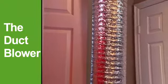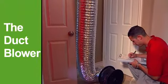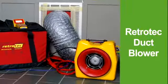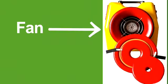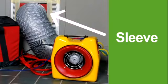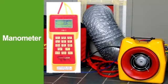We'll start by introducing you to this piece of equipment and then run through the procedures for testing total duct leakage. There are a couple different types of duct blowers on the market. In this video, we'll use one type, but it's not the only one available. The typical duct blower kit consists of a fan, which blows air into or pulls air out of the duct system, flow rings, which control fan pressure, and a sleeve and coiled duct for connecting the fan to a return register. A control knob lets you vary the fan speed, and the manometer reads duct pressure picked up by the static pressure probe.